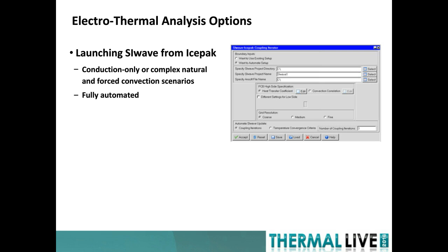I would have to follow up with an SIwave expert to get a certain answer to that. But I don't think there's too many issues with bringing in different file formats. It's pretty universal in what file formats can come in. But for this particular file format, I'd have to confirm. Maybe I can follow up with this user. Okay. I can answer that partially, I think, and that is one has to flatten out all the entities and then convert them from GDS to DXF, which is probably the preferred route.